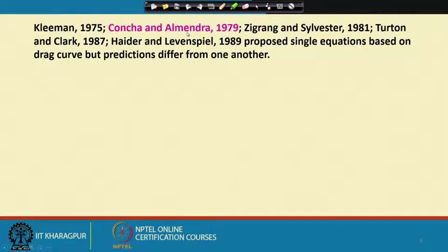Possibly that is the reason that if I take a synthetic set of particle sizes or densities and try to predict the free settling velocity at different size or density combinations using these models, then ideally, if all the equations are fundamentally right, the predictions should be identical irrespective of the model.